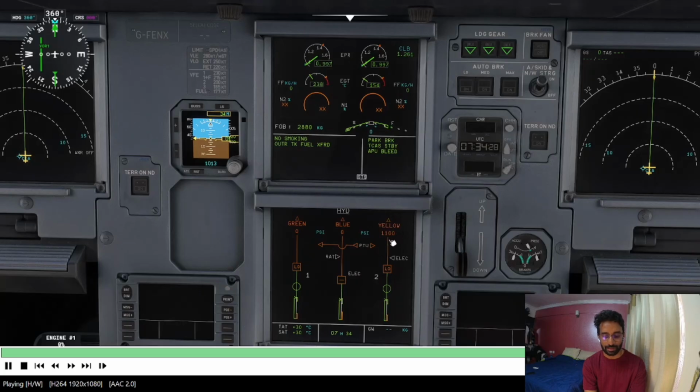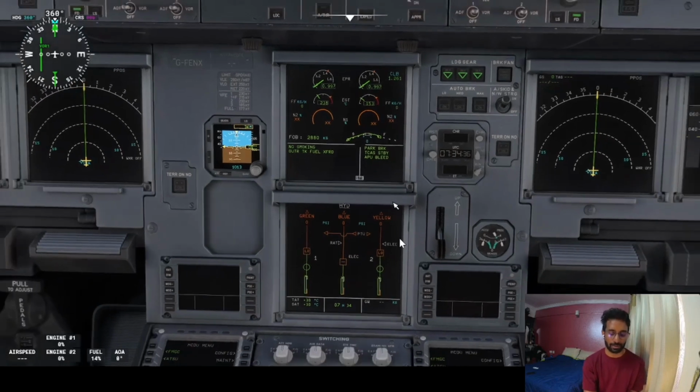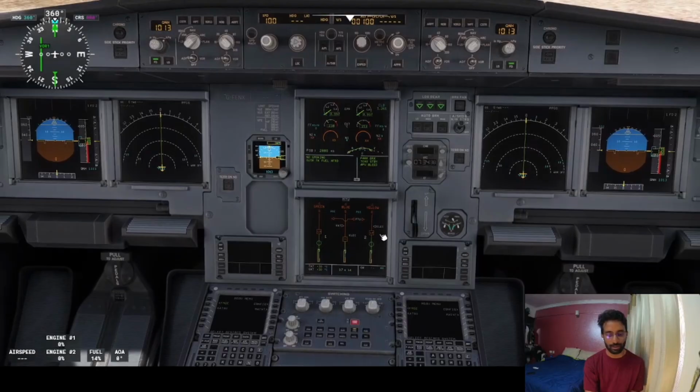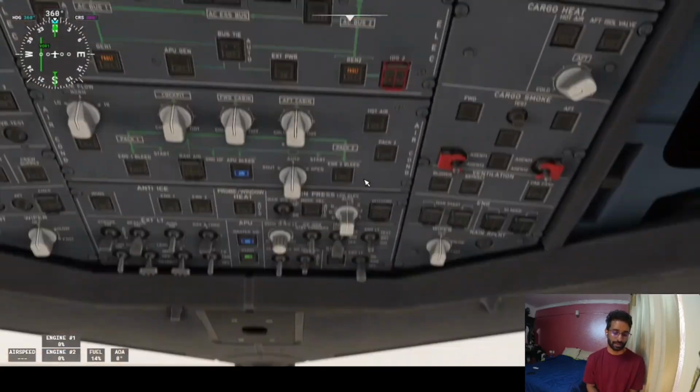Is this clear? Now the yellow pump turns off automatically when the cargo door is fully open, and it is still at 1. See, and it is very instant. You don't even have enough time for it to fully retract, because when the cargo door is open, the electric pump turns off on its own. So this is not right. This is incorrect. Dangerous. Something happens, you are at risk.